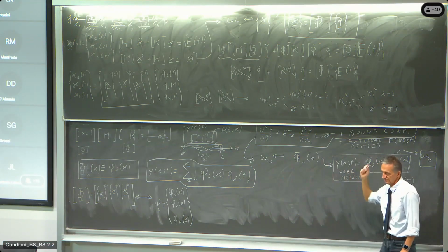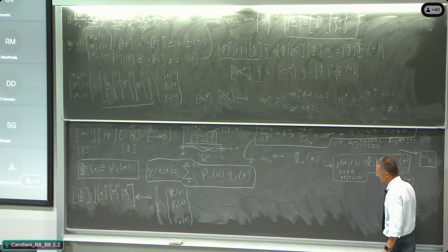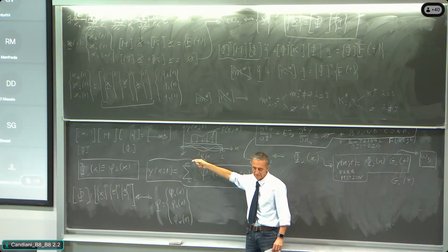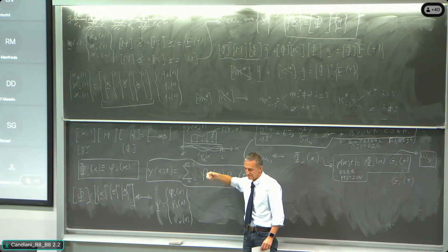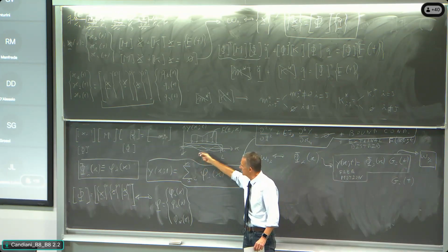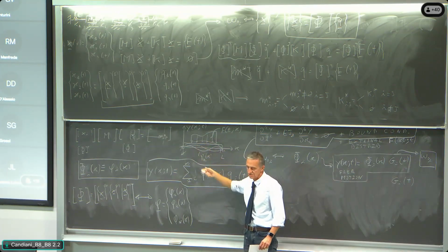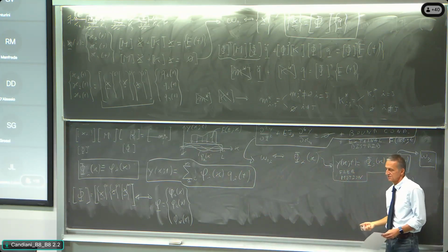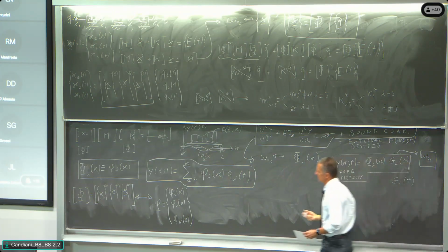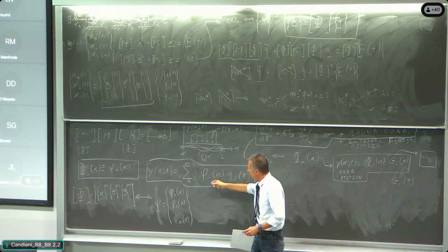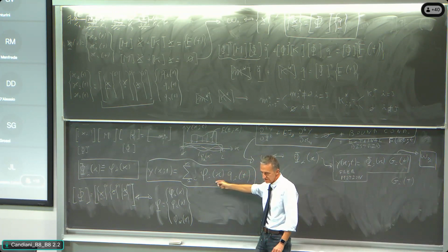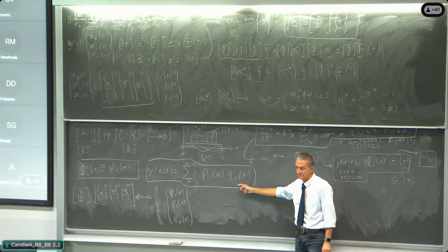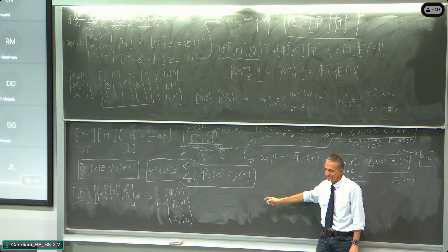The free motion is disappearing, because the system is always damped a little bit. You have an excitation. The excitation is arbitrary, and so the movement of the system. We pretend to say that the movement of the system is represented by a superposition of the modal shapes, each of them modulated by a time domain function that is, and here is the point, the unknown of the problem.